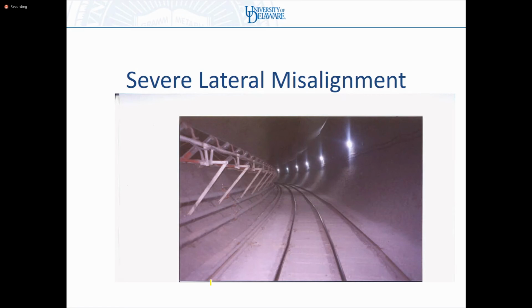It happens to be due to a weld, but I don't care, because whatever causes the surface variation causes the surface variation. I can very easily have surface variation from bad joints or bad welds as I can from failed sleepers or from the support being bad or whatever. I only care that there's a variation in height at the top of my railhead. So you can definitely have a variation in height in the top of your railhead in embedded track.